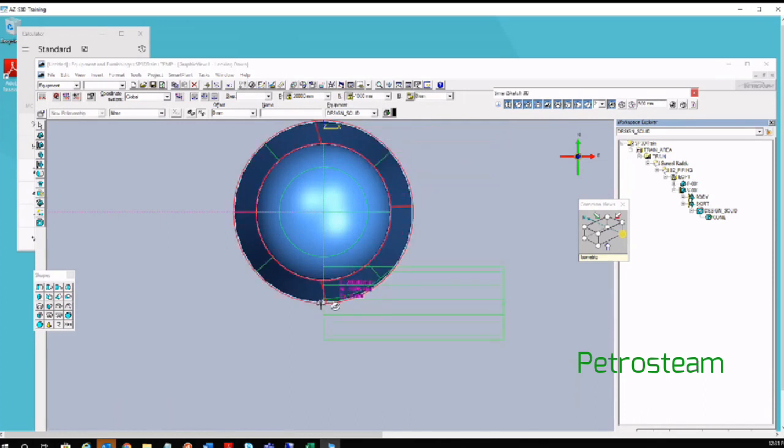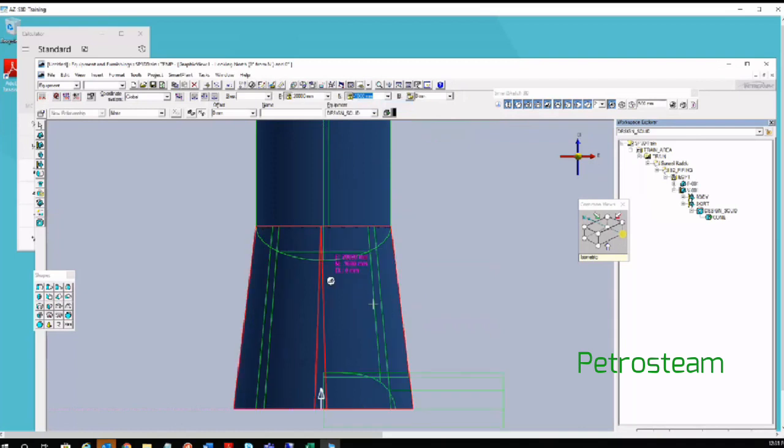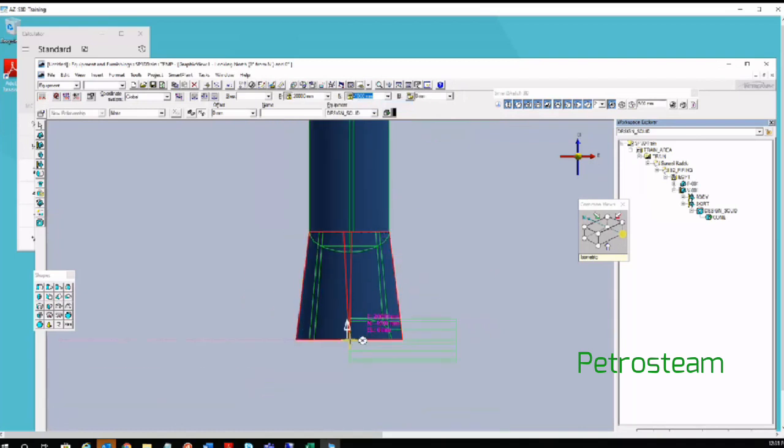Okay. And then in front view, you should fix the elevation. So this is your zero elevation. This height is 2 meter. If you want to take the through hole exactly at the center, put the elevation as positive 1 meter. With this, you have fixed your location for the cylinder.